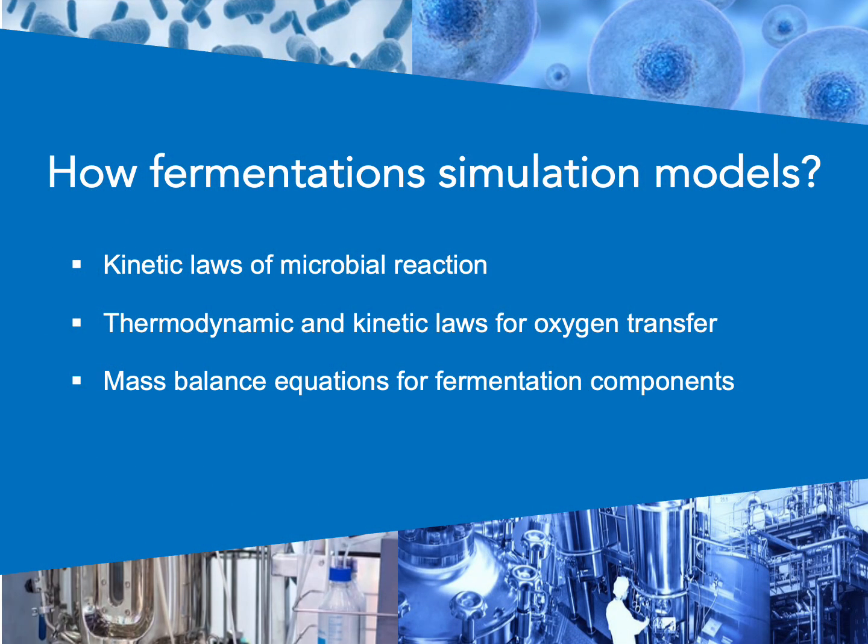In this tutorial, we will explore how to construct a simulation model of fermentation processes. You will learn how to integrate the kinetic laws governing microbial reactions, the thermodynamic and kinetic principles of oxygen transfer, and the mass balance equations for key fermentation components, to predict the time-dependent variations of substrates, microbial biomass, and metabolites throughout the course of a fermentation.